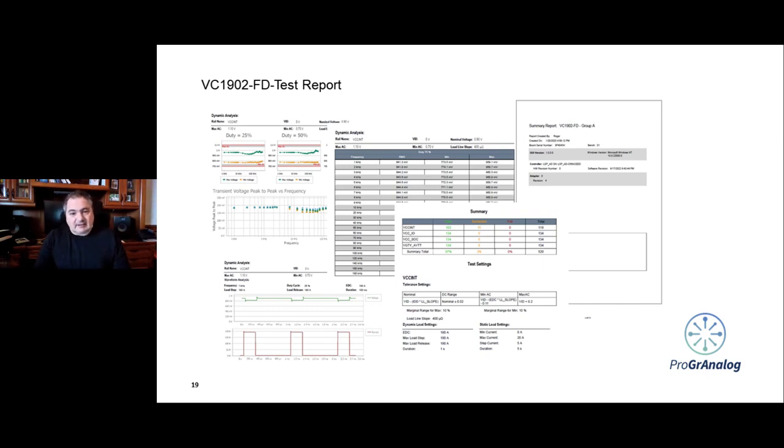Obviously, everything we send out is calibrated and measured, and there's an annual calibration. But you want to be able to coordinate it with an oscilloscope because you might want to take a measurement somewhere else on the board. You're busy debugging other elements of the board, right? So you want to be able to get a trigger from us and trigger an external oscilloscope. You want to be able to sequence an oven, do some oven testing, or use a variable bench supply powering the input to your power supply. You want to be able to sweep that so you get some margin. How can you do corner testing without putting your system through the corners?